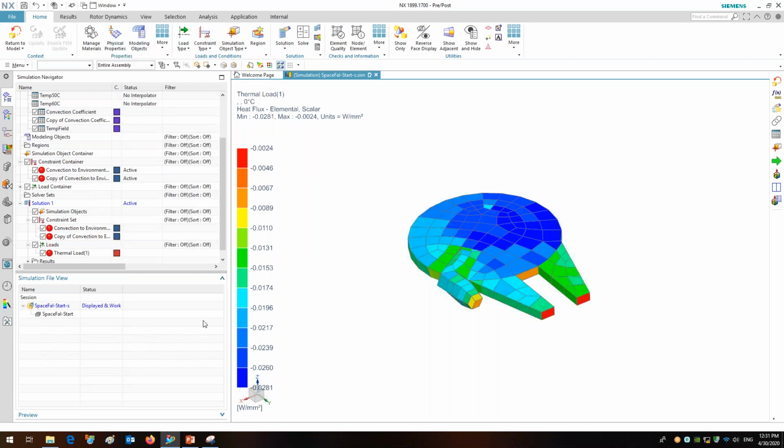So what we've done here is created a heat flux that is spatially dependent and temperature dependent on the wall temperature and a fluid temperature. But let's say you have a slightly different relationship for your heat flux. You might have something that is actually a temperature and time dependent heat flux.